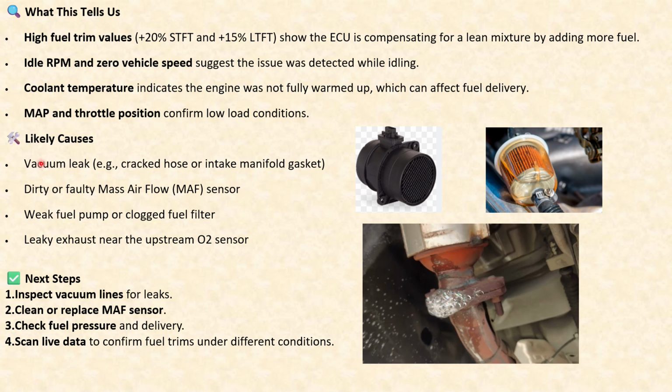All right, so the likely cause is a vacuum leak, maybe a cracked hose or intake manifold gasket, or a dirty or faulty mass airflow sensor. There's a good chance this is happening. Other causes are a weak fuel pump or clogged fuel filter, and a leaky exhaust near the upstream O2 sensor. So these are all the likely causes, and this is exactly how, by seeing the freeze frame data, a technician can infer where exactly the fault is or what the likely causes are.